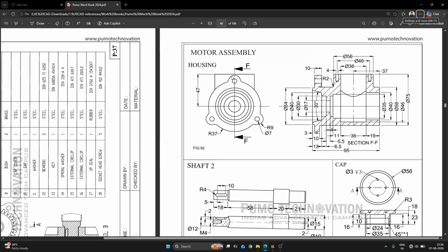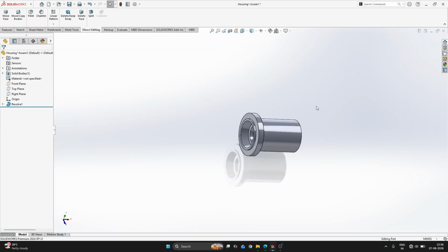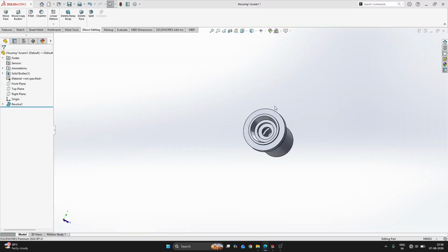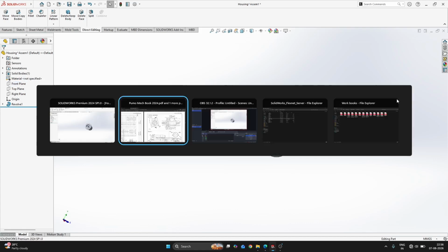So if I want to do this protrusion and then this hole, I need to do it in a second step. Okay, so let's do this now. I'll just use the plane again. I'm not going to create any new plane.